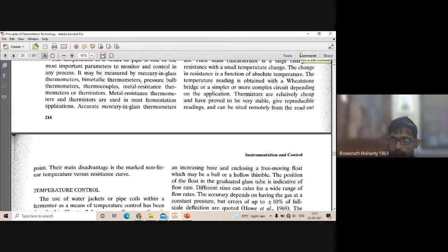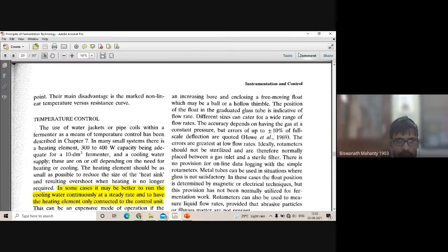So please understand that when you are talking about any fermentation process and you are passing some cooling liquid, the temperature change is not instantaneous. Okay, temperature change is not instantaneous. So we need to have always a temperature control liquid flow at basal level. So for example, I need 25, so always some 25 will go. If there is some atmospheric change, then temperature will bring down. So cooling liquid temperature they maintain, and it is not as per requirement, but a continuous flow is generally inducted in a large scale fermenter or bioreactor process. So these things you will do.